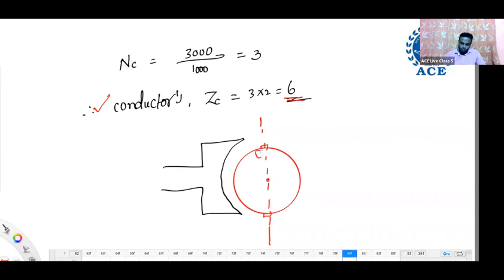See, the armature ampere turn per pole. So in this half, what is the armature ampere turns? It is 4000. Armature ampere turn per pole is 4000, and this half is again 4000. Okay, per pole 4000. But the compensating winding is located in the pole faces here. There are some turns in this and current is flowing, the same armature current. But how much is this pole face covering? 75% they gave.